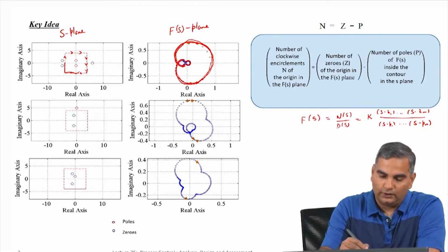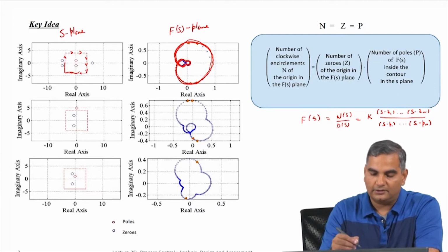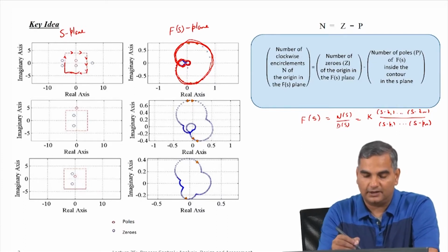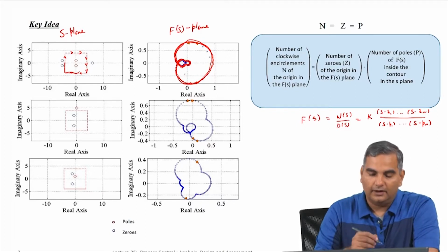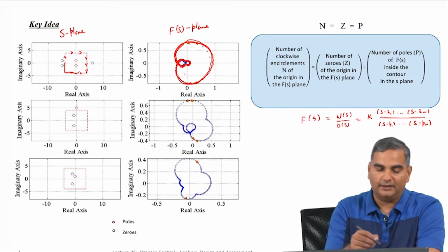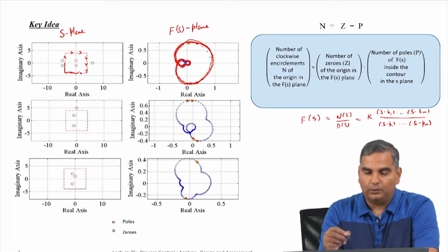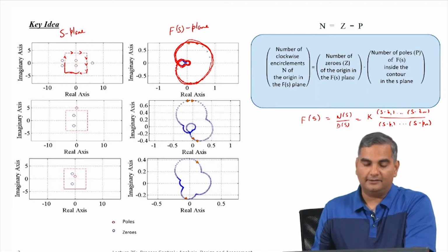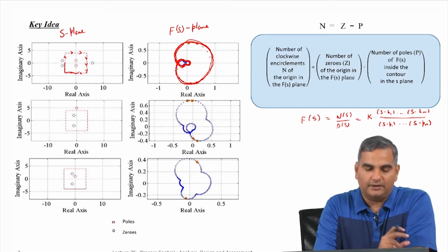So, I am here, so it still continues. Now, I go around and come back here. Now, forget the outer circle, from here to here I continue to circle and origin is inside. You will see I have made another circle again in the anti-clockwise direction around the origin. So, basically when I convert this contour, which is the clockwise contour in the S plane, to an F(s) plane, in this case I seem to have made two counterclockwise encirclements of the origin.